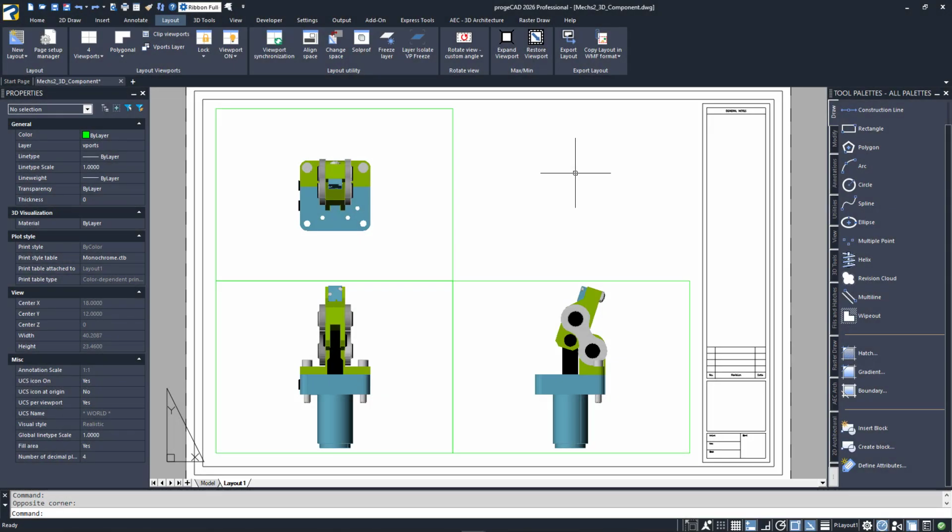Back in the first module of this series, we had a video that covered dimensioning your drawings. We used an age-old method of scaling our dimension features up by an inverse factor of the final scale and placing the dimensions in model space. While this is probably the oldest method, there are others. In this video, we'll use a different method, this time the dimensions being placed in paper space.